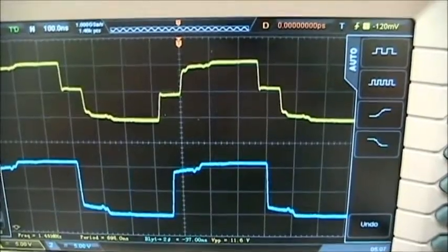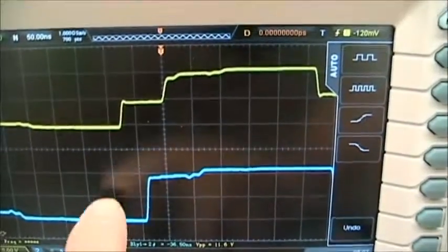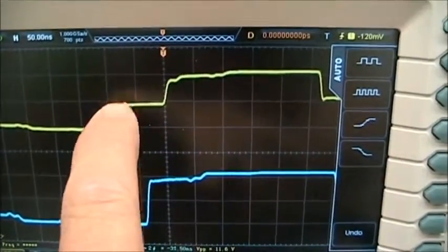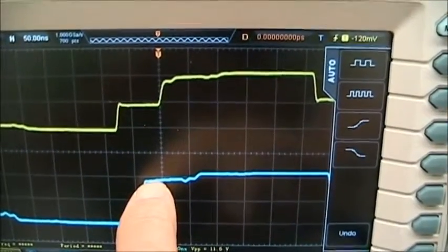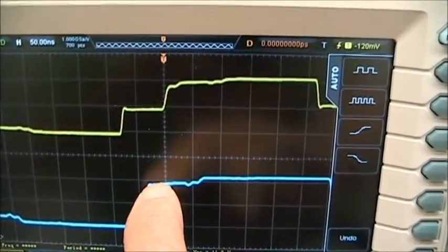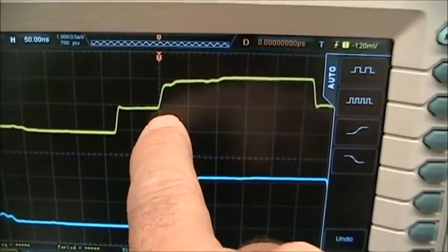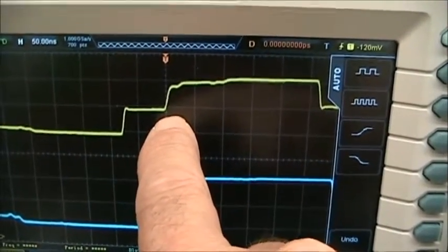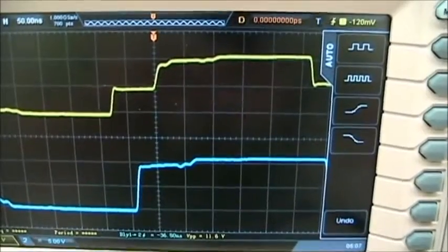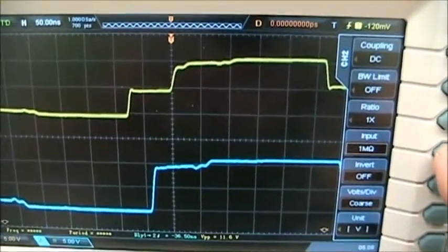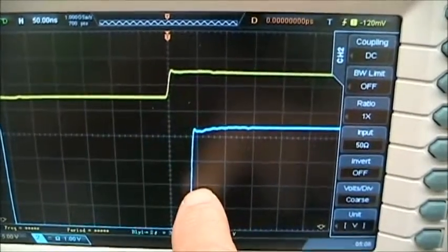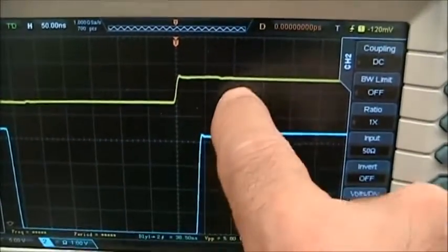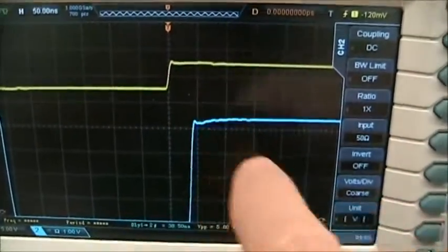If we zoom in, we can see that the input pulse rises. We see the next step at the output. Because it is an open, it reflects the energy back, and that energy appears at channel 1 at this time. I will change back to 50 ohms so you can see the change in impedance. Here we see the time delay, but we don't see the rising voltage from the second reflection.